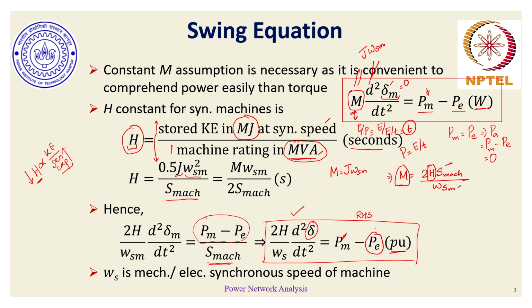With the same disturbance, the RHS effective term would remain the same, but with high renewable penetration, as discussed here, the value of H would go down. So it is likely that the corresponding double derivative term sitting over here will take up a higher value in case of higher renewable integration, specifically solar PV and energy storage systems, compared to a case where renewable integration is lower. Because in that case, the corresponding H value would be higher, and with the same disturbance, the RHS term more or less remains the same.